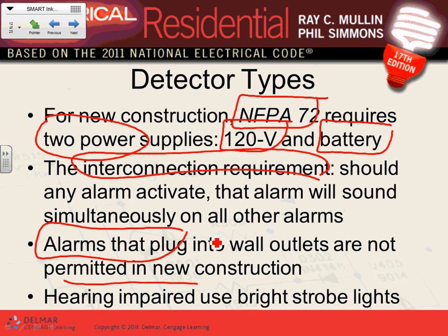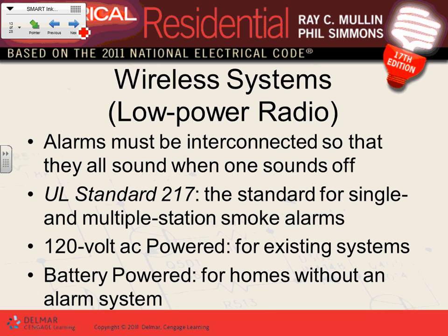If you have people who cannot hear, they have brighter strobes for them. They have brighter strobes so that if you can't hear, you can see. That's why almost all of them have two alarms, a visual as well as an audible alarm. You have the horn and the strobe all in one. Anybody ever wonder why? If you can't hear, you can see, and hopefully it will also guide you to the exit of that building. Okay.